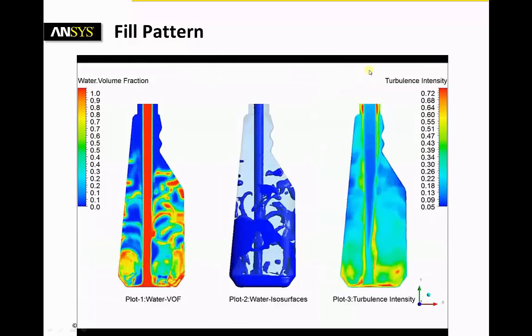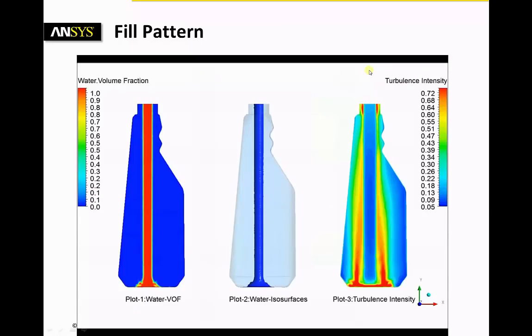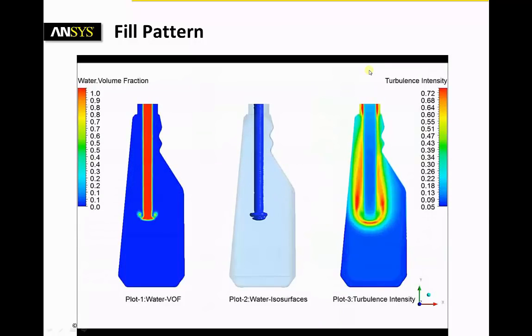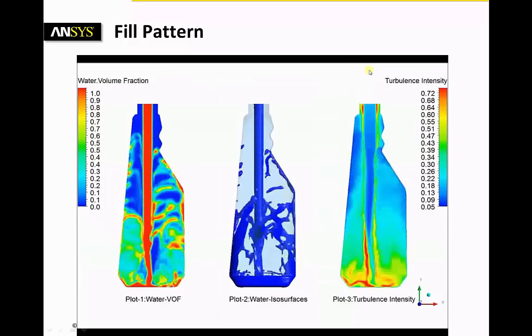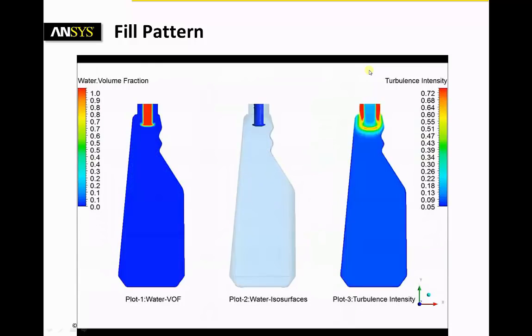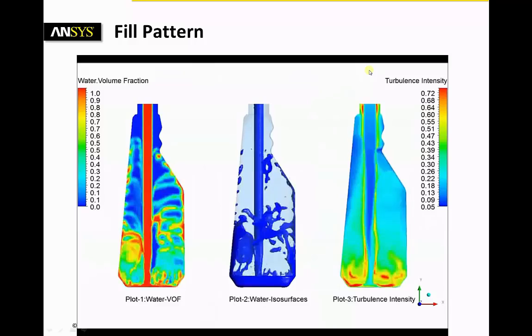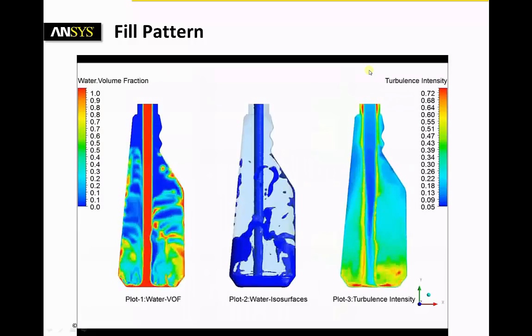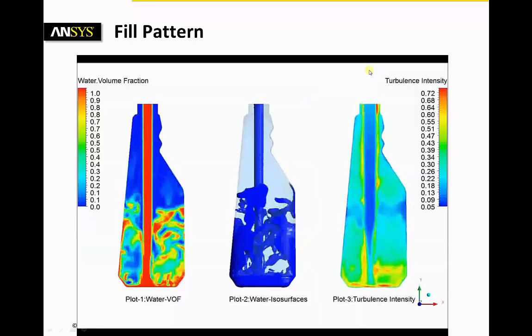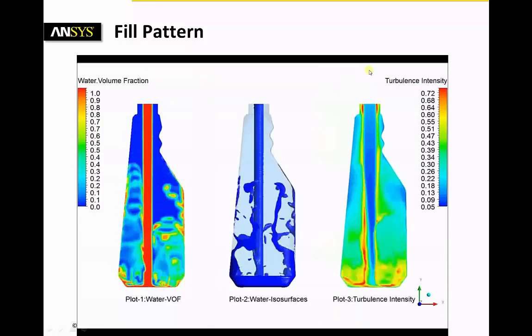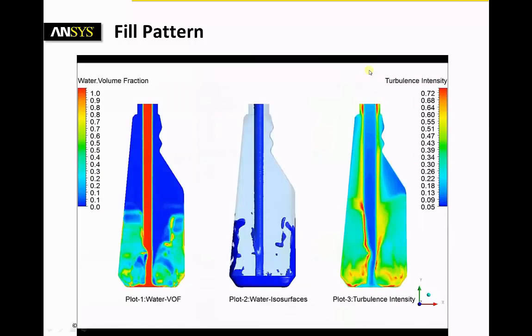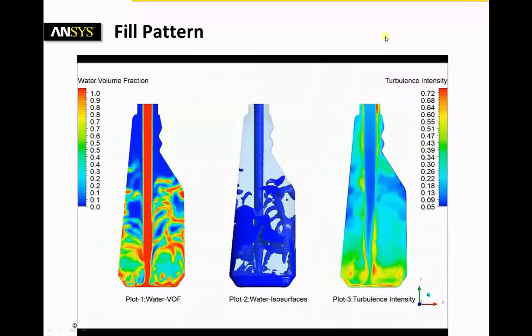Typically, it is desirable to decrease the cycle time to increase the productivity. But at the same time, the fill needs to be complete, and the level of turbulence needs also to be monitored during the fill process. Finally, the amount of gas trapped during the fill may also be important and could affect customer perception during the buying process.